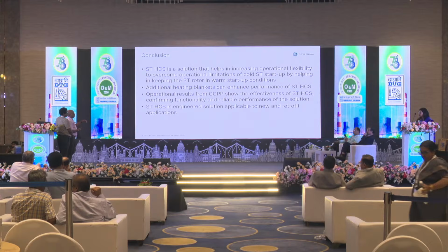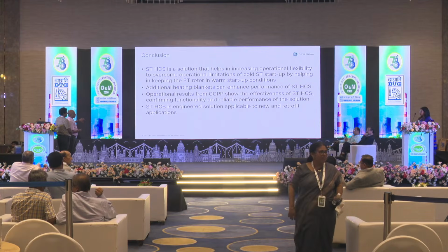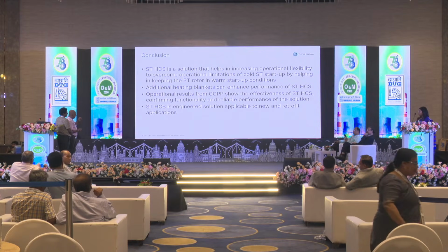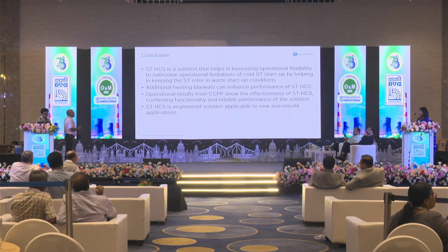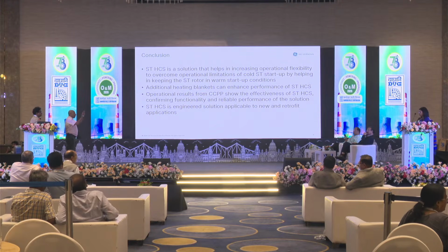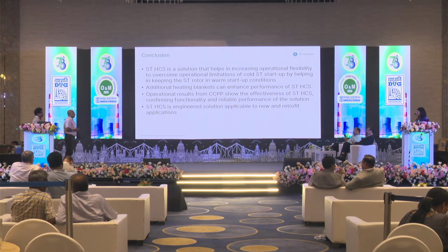Keeping aside the boiler, from the first steam injection in the steam turbine, normally it takes around 170, 180 minutes to get synchronized with the grid. Whereas in the warm start case, sir, it is almost 90, 95 minutes where you can start injecting the steam, reach 3000 RPM and sync with the grid. So that much time saving and that much cost saving we have seen, sir.